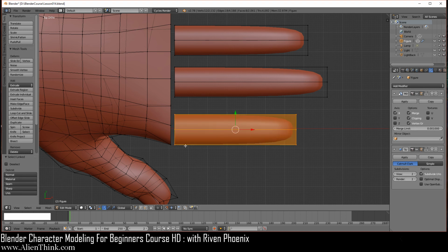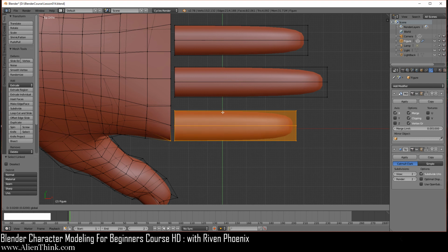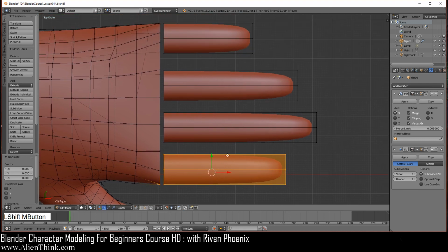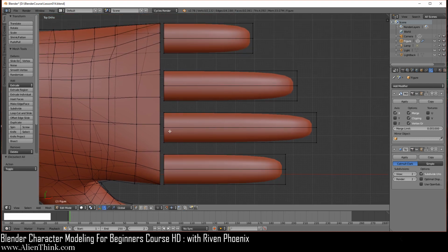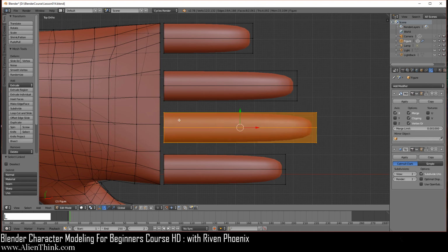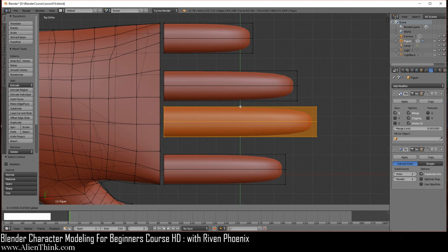It'll select it. Now press the C key and go ahead and select this vertex too, right over here. We're going to bring this in 1, 2, and then 3. Okay, and then A to deselect. Now press the L key near our vertex over here. It'll select this. Take this up 1, 2, 3, and then 4.